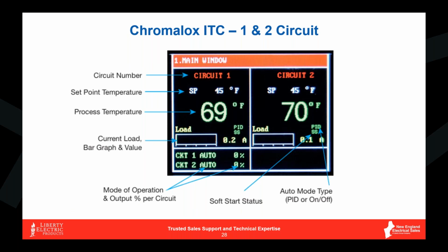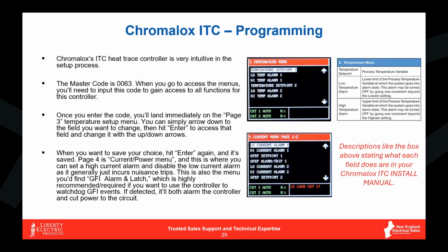Again, you can have alarm histories printed out off of this thing if you want to, or displayed. The one thing I really like, in particular, is that it integrates the GFI code protection, and it has that soft start feature. Soft start will also help extend the life of your cable slightly, because again, you're not whacking it with that full inrush current when you're applying heat to your pipe.